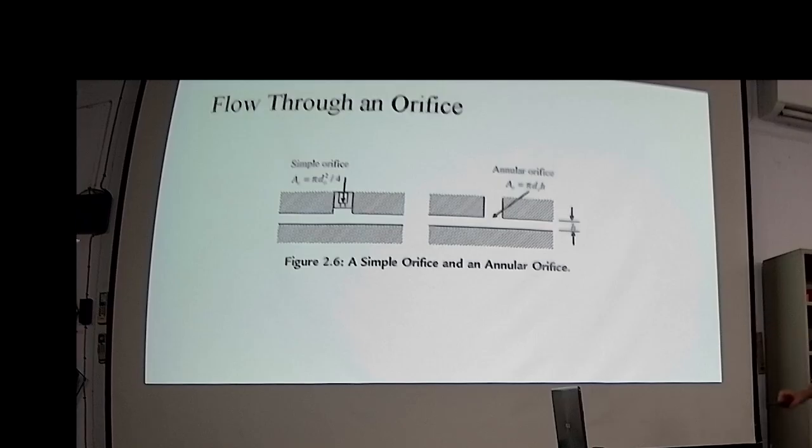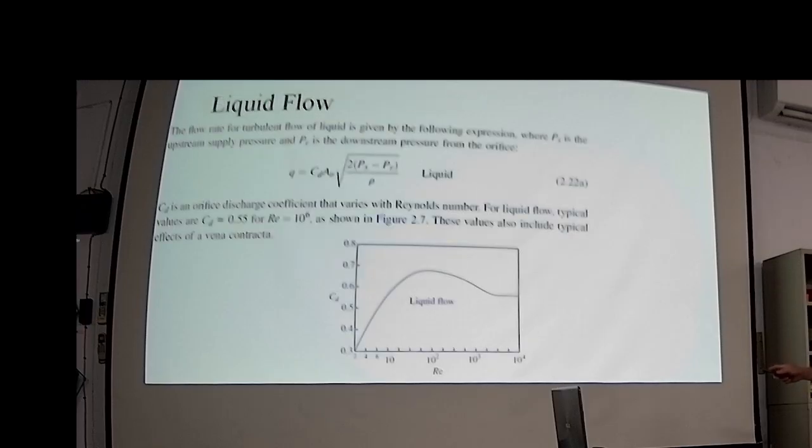So this one you should buy as a small component, an orifice component. And this one you can select, machining by drilling a hole with diameter d, with a PR. And the film gap thickness is H in this circular bearing.